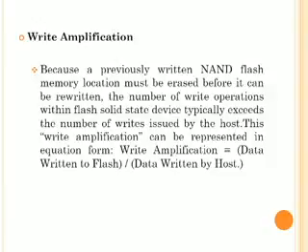Because a previously written flash memory location must be erased before it can be rewritten, the number of write operations within flash solid-state devices typically exceeds the number of writes issued by the host. This write amplification can be represented in equation form. Write amplification equals data written to flash divided by data written by host.